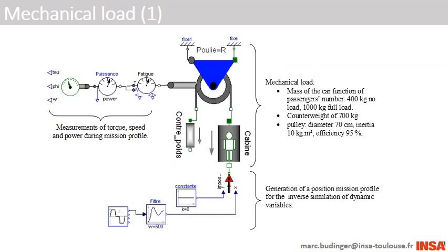The mission profile generator, completed by a second-order filter, can allow us to impose a certain movement to the mass which represents the elevator shaft. The carrying mechanism is realized thanks to a pulley and a counterweight. We neglect here the effect of the mass variation due to the cables. The counterweight compensates the weight of the shaft when it's half-loaded. The computation of torque and speed of the pulley can be done by using inverse simulation or by implementing calculus in MATLAB or Excel.